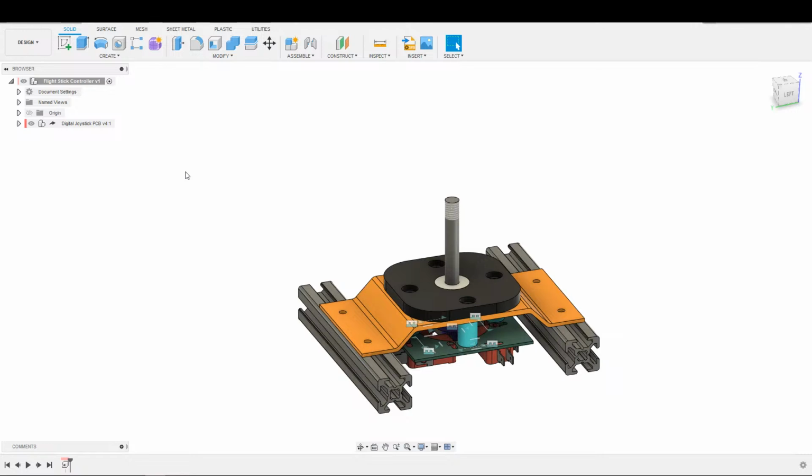Point B is that after I was done fixing my design mistake with the gearbox, which took me something like 12 hours and 3 different prints, the whole idea of using a rubber band with this setup does not work. The second you put any amount of load onto the decoiler, the rubber band just starts stretching, and it puts so much pressure on the input of the gearbox that it stalls out the gearbox instead of turning the